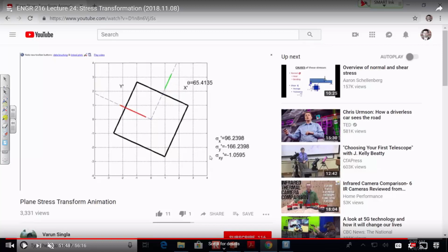Now, I'm not going to try to re-derive Mohr's circle for you, but the nice thing about the formulation is that when the shear stress becomes 0, the normal stresses reach their maximum. That's really the benefit of Mohr's circle: it determines the maximum possible normal stress, and that happens when the shear stress equals 0. So how do you formulate Mohr's circle? You do some trig, and you take the derivative as the shear stress approaches 0.